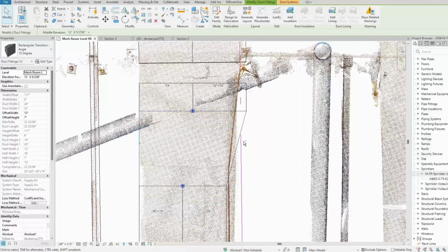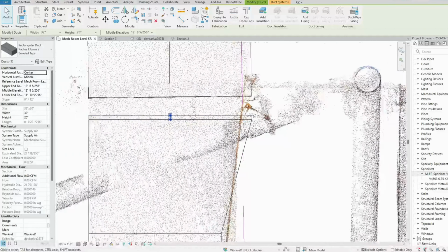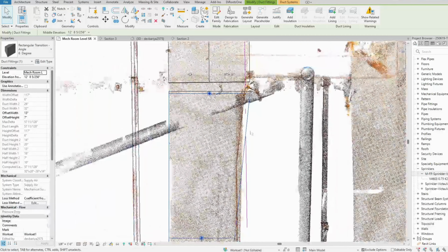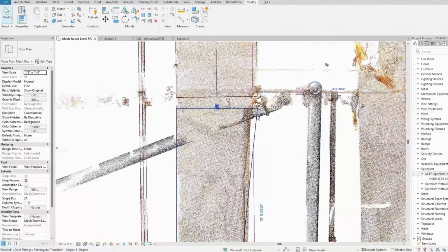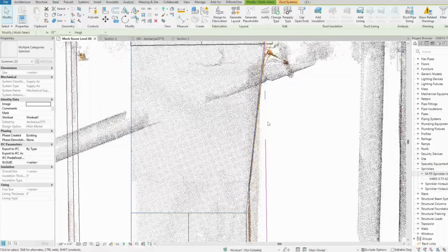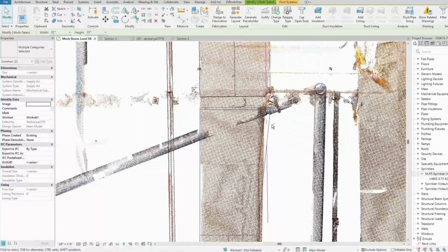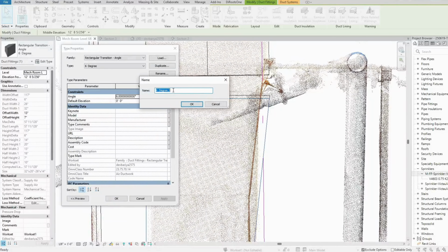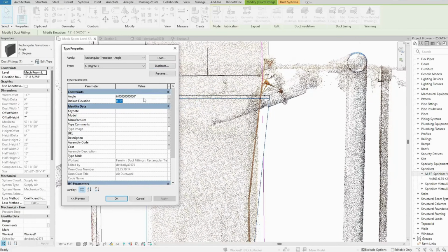Now let's talk about how ducts connect with other elements. If you're placing ducts to supply air to a room, you'll want to connect them to air terminals, like diffusers or grills, and to mechanical equipment like an AHU or FCU. Revit uses connectors placed in each family to enable ductwork to snap into place automatically. If your ducts don't connect right away, try zooming in and make sure the connector face aligns. You can also use the Trim, Extend to Corner tool to join ducts manually.